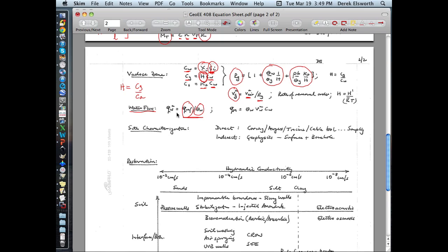If you know the advective velocity, so this is the Darcy velocity, which is moving from, if you want to calculate the rate at which it's moving, the mass loading of the system, then you take the advective velocity times the volumetric moisture content, which gives you the Darcy velocity of the water. Darcy velocity times the concentration gives you the mass loading rate per square meter, basically.